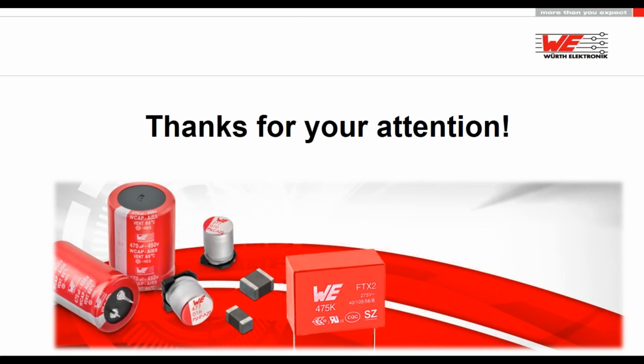But in general, we don't have this in LTspice for all the caps. We have LTspice models and everything already. Also, we have this REDEXPERT tool where you can find a lot of things like ESR over frequency. So for all our aluminum electrolytics and polymer caps, we also provide ESR over frequency range, which is a very nice tool, and these are based on real measurements.